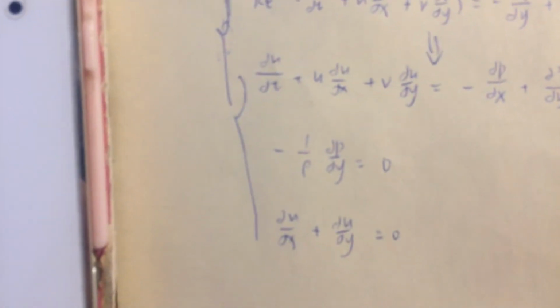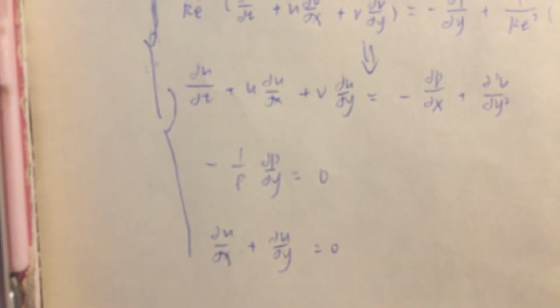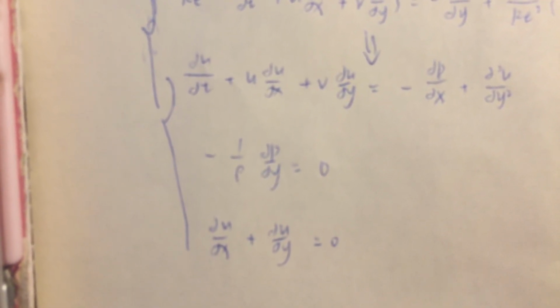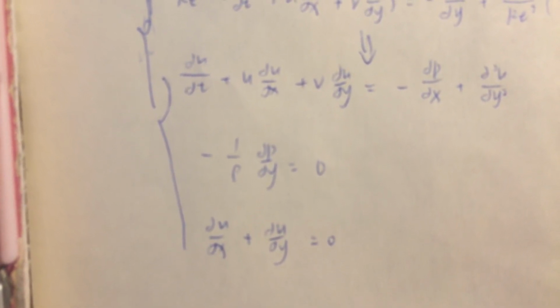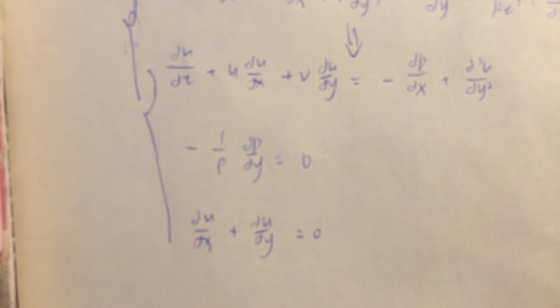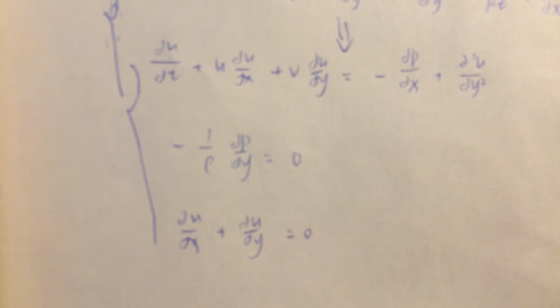Moving up from the wall, the flow first moves backwards against the mainstream, but further from the wall it must again turn back to join up with the mainstream. So the velocity gradient must accordingly be negative right at the boundary in the reverse region, and the wall stress vanishes, which indicates that boundary layer separation may happen.